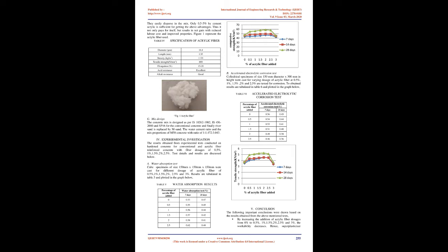D. Water. Water should be free from acids, oils, alkalis, vegetable or other organic impurities. Soft waters also produce weaker concrete. Water has 2 functions in a concrete mix. Firstly, it reacts chemically with the cement to form the cement paste in which the inert aggregates are held in suspension until the cement paste has hardened. Secondly, it serves as a lubricant in the mixture of fine aggregates and cement.